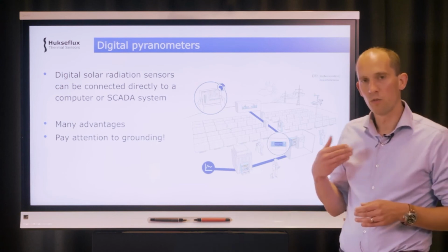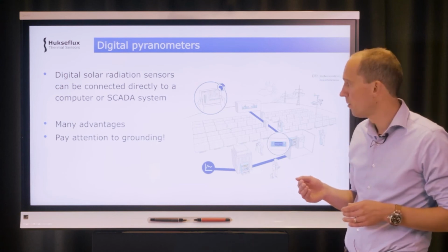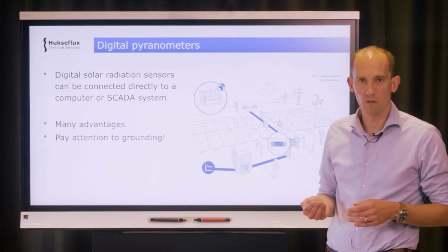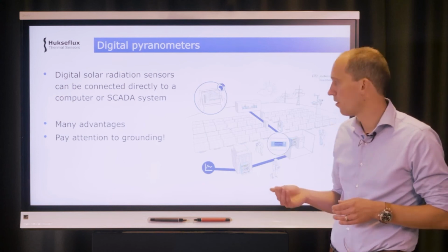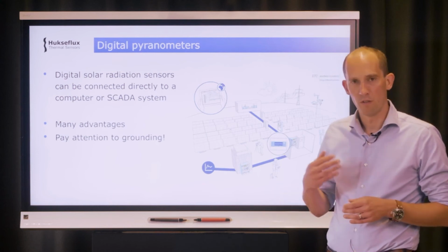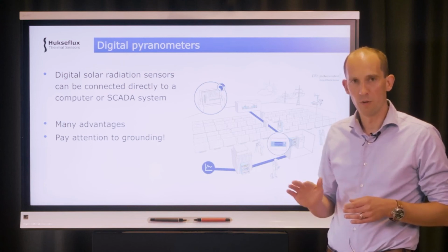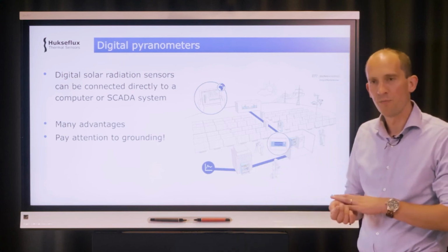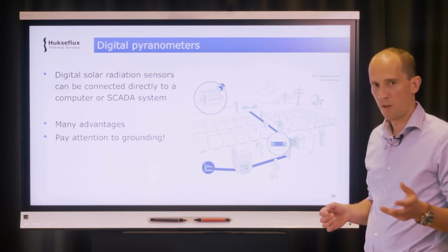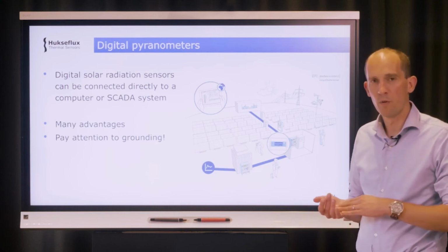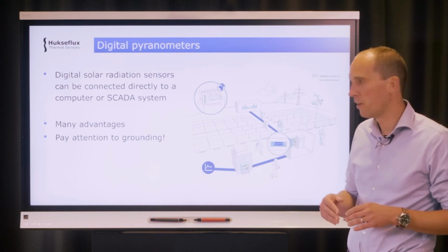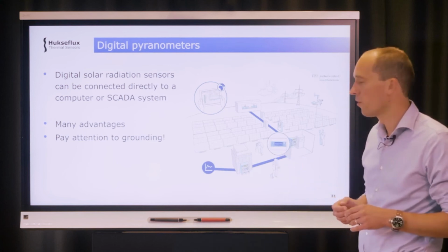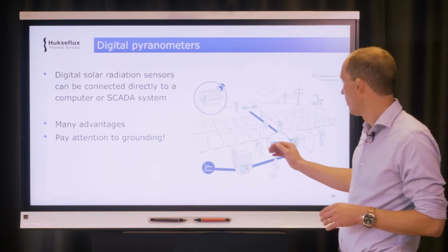Whenever you install digital instruments of any kind, you have to pay attention to the grounding of your instruments. These are very sensitive measuring instruments, often installed in situations where you have high currents. We have a lot of literature available, we have some recommendations in our manuals, and when in doubt, please ask us for instructions.